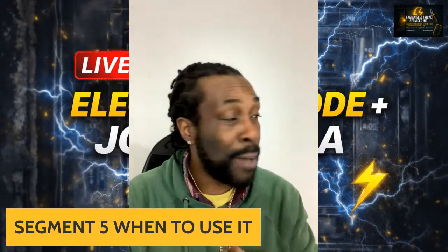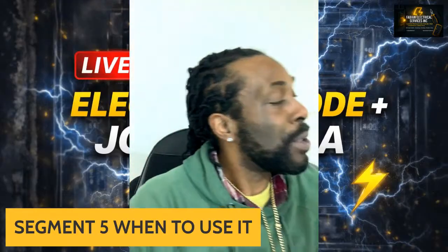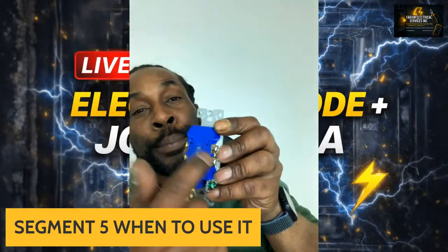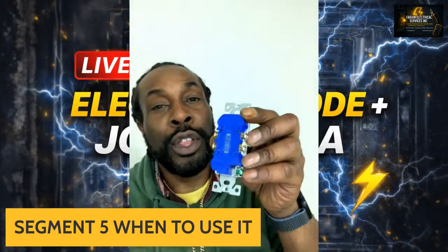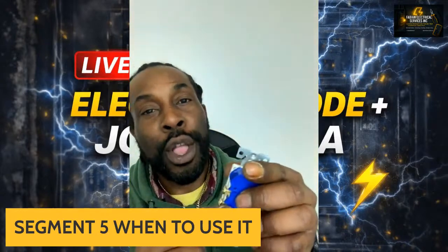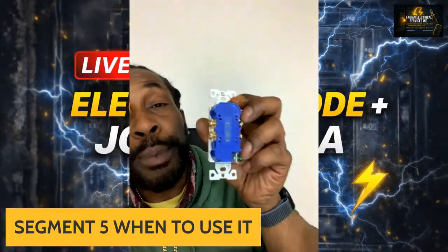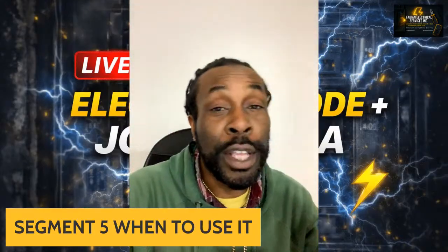And what backstabbing is, basically, is when you take your wires and you pop them into here. You'll find that these connections are not as strong as when you screw them on. Again, this is a faster way to do your receptacles, so a lot of times people will backstab into here. There's nothing wrong with it.